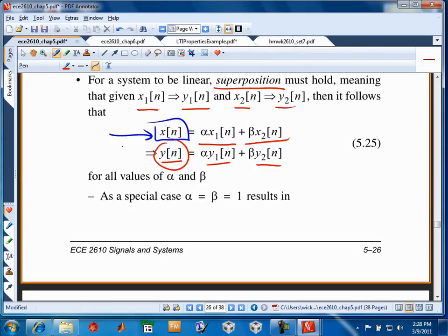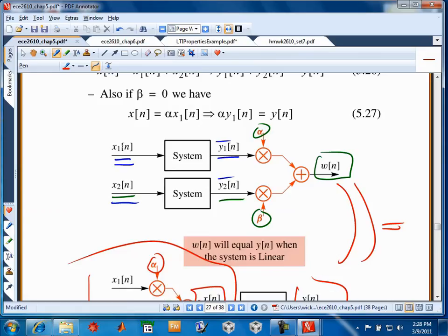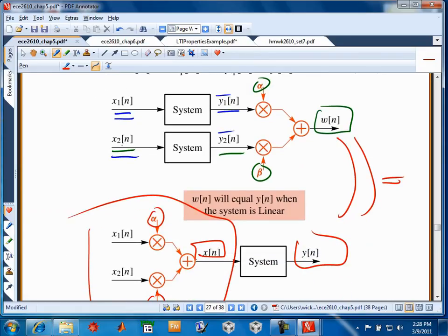Likewise, in the linearity, if you think it's not true, you could just prove it for a particular value of alpha and beta, like 1 and 2 or something like that. You don't have to establish it for any value of alpha and beta. And of course, in real processing systems, whether they be digital or analog, alpha and beta have to be bounded in some way. Because in the karaoke system, making alpha and beta too large led to the distortion in the output, right?